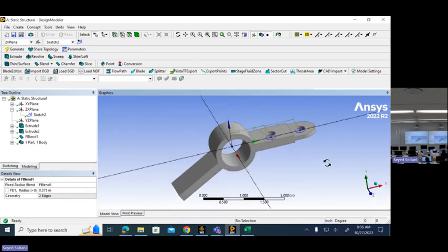Before we do this, we have to make sure which base plane the new plane should belong to. So my base plane here would be this plane. And I want to rotate it so that it will be aligned with this surface. So the base plane in this case would be XZ. Right? So then again, I have to create a new plane. I have to click on the XZ because that's my base plane. And there's an option right here if I can find it.